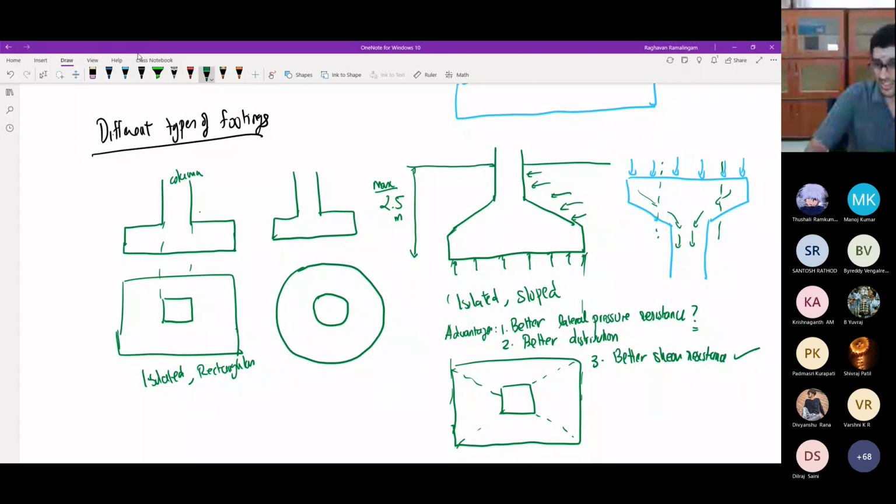But for this question also I can tell you, I want good shear resistance, so why not, instead of keeping it like this, make a bit thicker footing to have the same shear resistance as this. So the material used is less over here. For the same material, to achieve the same shear resistance, you are sloping it. Okay, fine. Good. Shear resistance is better.